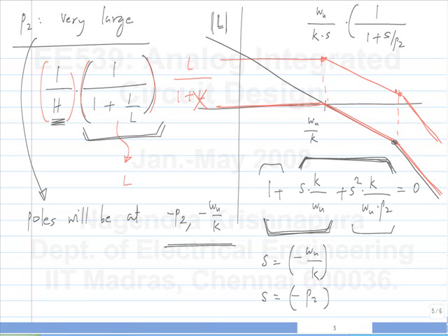So if you have a certain parasitic pole, you can think of it as a condition on the unity loop gain frequency. Okay. So the unity loop gain frequency has to be a certain factor below the parasitic pole, or when you are designing, you want to design for a certain unity loop gain frequency because you want a certain closed loop performance. So this is the condition on the parasitic pole. Now, in a given technology, there is a limit on how high a frequency you can make a parasitic pole. So you will not be able to design for greater than a certain unity gain frequency. So that's the technological limit.